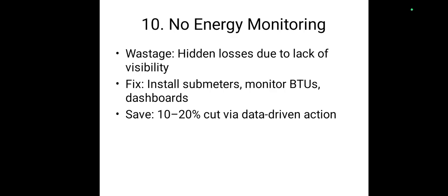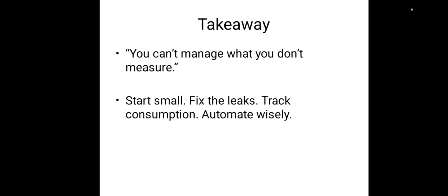No energy monitoring: hidden losses due to lack of visibility. We can install submeters, monitor BTUs and dashboards. We can save 10 to 20% of energy. You can't manage what you don't measure, right? So you can start small: fix the leaks, track consumption, automate wisely.